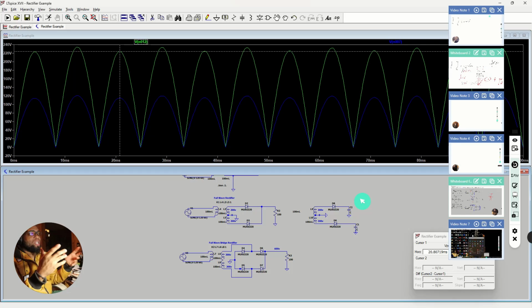You don't want to put all that energy into a resistor. You say, oh, I'll just put a resistor there and it'll bring down my voltage. But then that thing is going to be burning, you're going to dissipate a lot. It's just inefficient to do it that way. So what would you do before you would think about doing it with a resistor? You would do it on your rectification end, which is using half the winding and stuff like that. So this is why this stuff is important.